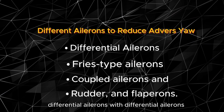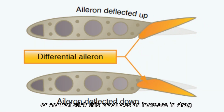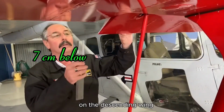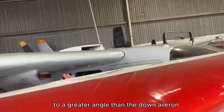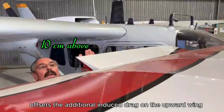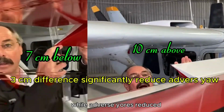With differential ailerons, one aileron is raised a greater distance than the other aileron is lowered for a given movement of the control wheel or control stick. This produces an increase in drag on the descending wing. The greater drag results from deflecting the up aileron on the descending wing to a greater angle than the down aileron on the rising wing. This slight increase in drag of the downward-going wing offsets the additional induced drag on the upward wing, helping to balance the resulting yawing moment. While adverse yaw is reduced, it is not eliminated completely.